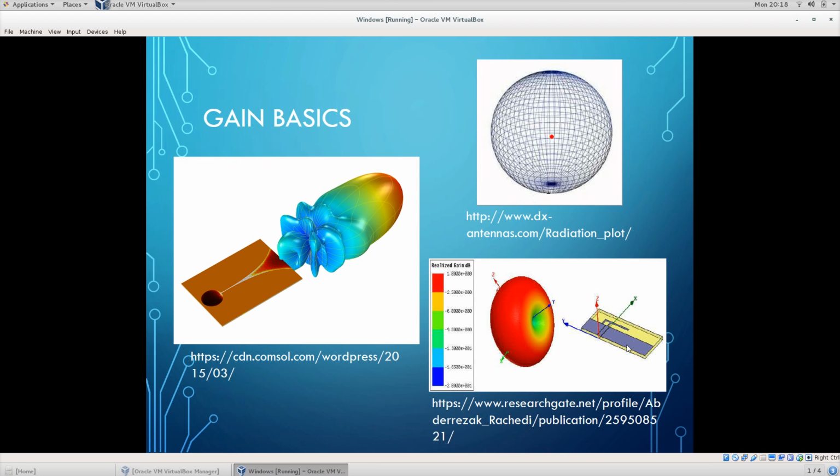Now if you haven't seen this kind of thing before, you might be thinking, well, if I want an omnidirectional antenna, why wouldn't I just go for something that's really omnidirectional, like something up here, right? So this item here that you're seeing is a representation of what's called an isotropic radiator. Now I spoke a little bit about that earlier with dBi, decibels relative to an isotropic radiator. But the idea behind an isotropic radiator is that it is a theoretical perfect antenna. 100% of the energy that is present at the dot in the center is radiated into space. So one way to think of it is that as the waves move away from the center, it's kind of like blowing up a balloon.